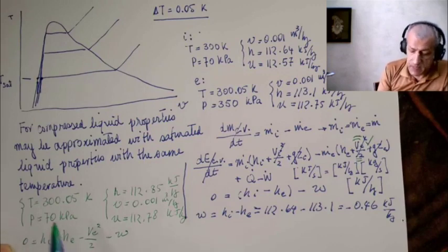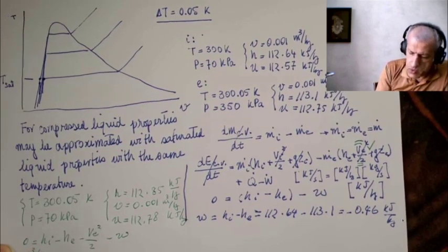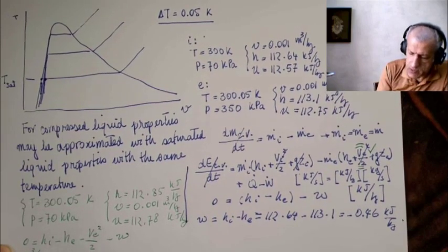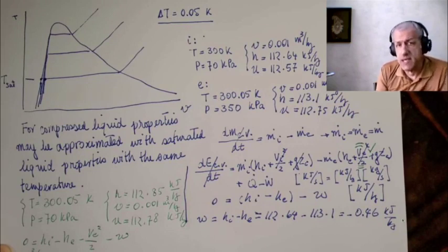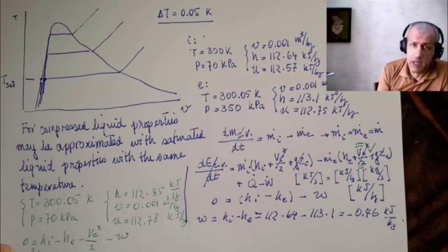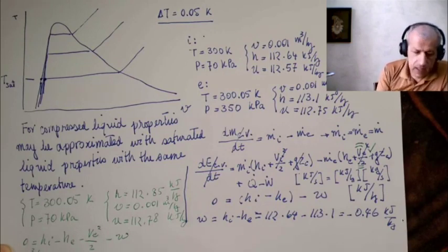This is just the same thing. So v_e squared over 2 times 1000. Remember, please, there should be 1000 here because v squared over 2 is in joules per kilogram. It is square meters per square second, which is equivalent to joules per kilogram. And just to get kilojoules per kilogram, which is the unit we usually use, we should add 1,000 here.